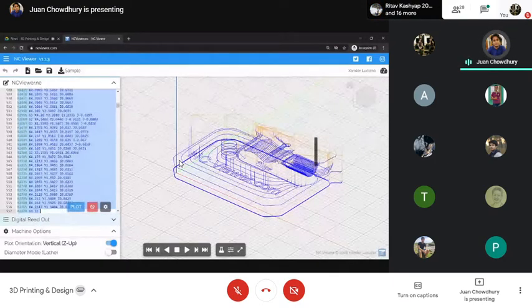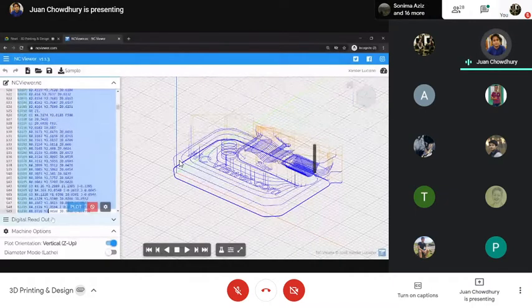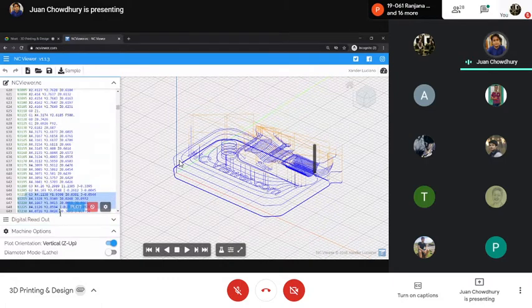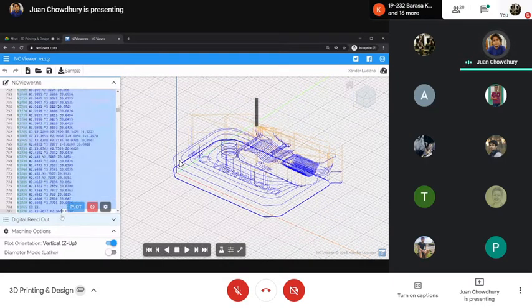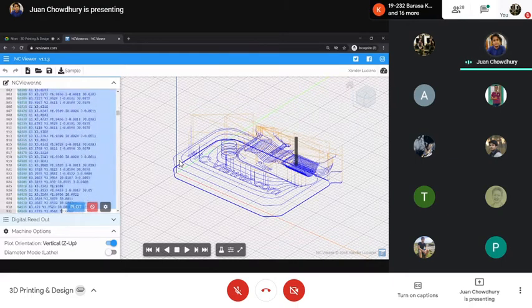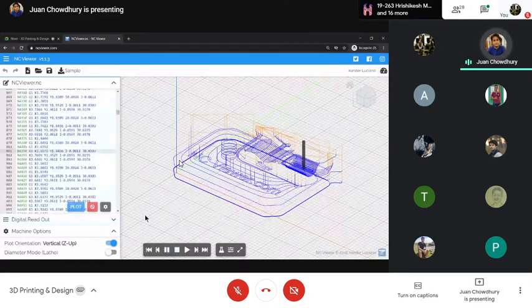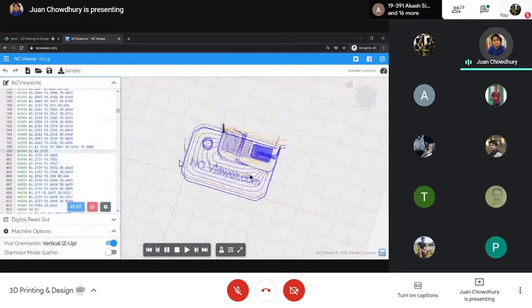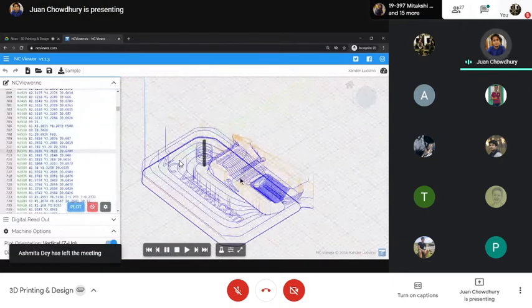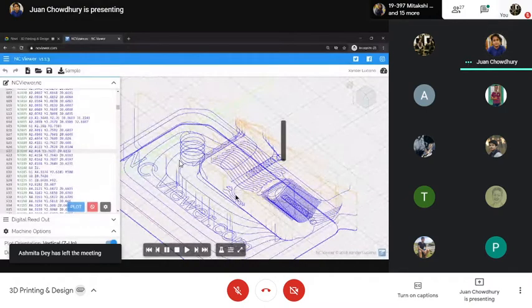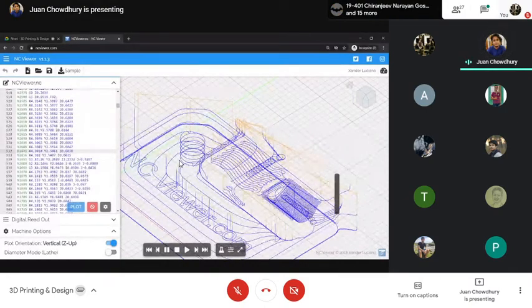Why is this important? Say you are working on a really large scale platform, the terrain is not flat, or you're using cement to build houses. It's convenient to simulate what sort of extrusion or path trajectory you have generated. You can take it back to the origin and it shows the 3D printing process, how the G code and M code move. It doesn't matter if it is a 3D printing process or a CNC machine. And you can write your own code over here, by the way.